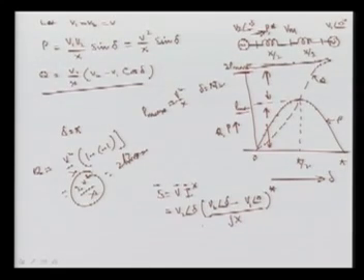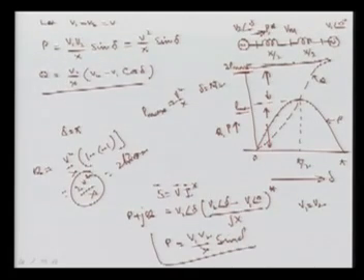If you go for the real and reactive parts separately, for this case let us put V1 equal to V2, and you will get the previous equation. This is nothing but P plus jQ, so you can separate out the real and reactive powers from this expression. We get, of course, P as V1 V2 upon X sin delta as in the previous case, and Q we get as this expression.